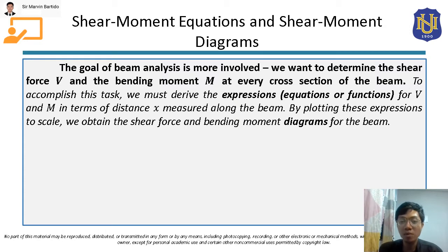Okay, so to accomplish that, we must derive the expressions, equations, or functions for V and M in terms of distance x measured along the beam. Again, class, these expressions, equations, or functions can be derived from the equilibrium equations for shear and for moment. And also, class, by plotting these expressions, equations, or functions to scale, we obtain the shear force and bending moment diagrams for the beam.